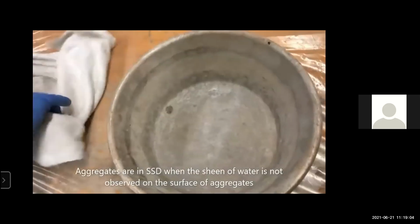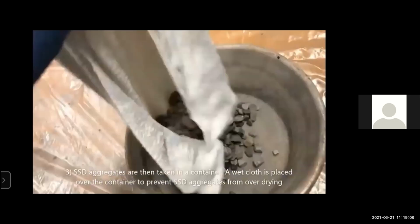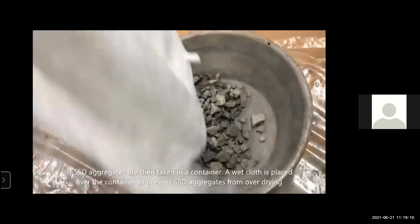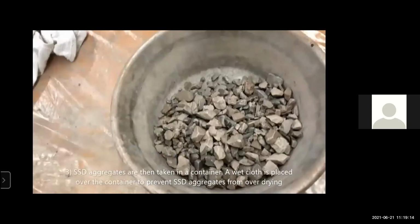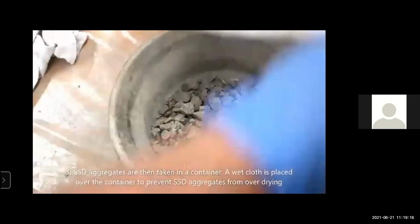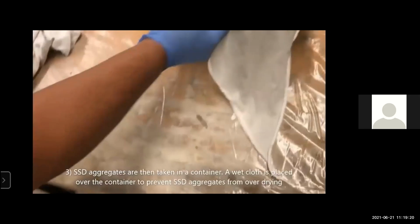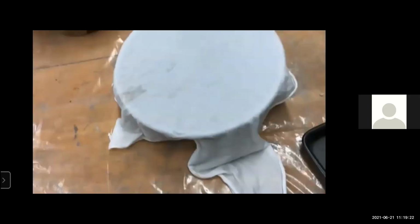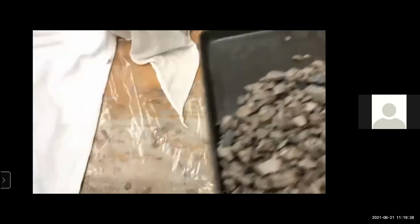So here if no water is present in the aggregate, then the SSD aggregate is taken in a container. A wet cloth is placed over the container to prevent the SSD aggregate from over drying. So here we put a wet cloth and cover this sample where we pour our aggregate in.